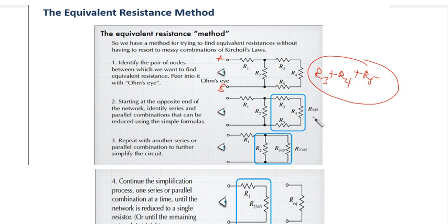So we can call that R345. That is the total resistance for 3, 4, 5 because they are in series. So by the time you reduce that, you're going to have a single resistance value, which is the resultant of these three resistance values that have been resolved in series. So you now have R345 as the resultant of this. So you have dealt with the first series combination that is encountered.